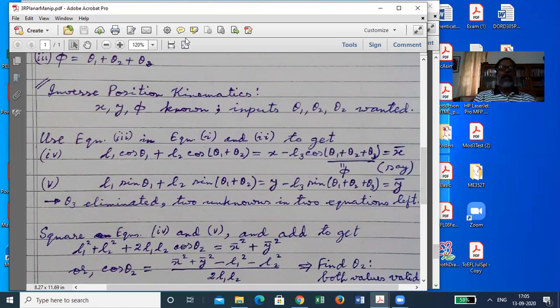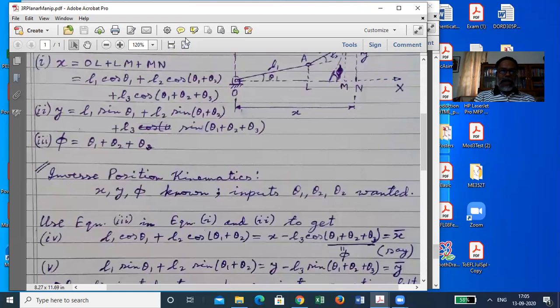So basically, you would need to solve these three equations for theta1, theta2, and theta3. And that means that here x, y, phi, this side will be given. L1, L2, L3 are anyway design parameters. They are known already for a particular manipulator. You would have to find out the particular theta1, theta2, theta3 joint variables required for that configuration in which the hand will reach the desired position and orientation. So you have to solve these three things with respect to theta1, theta2, theta3.